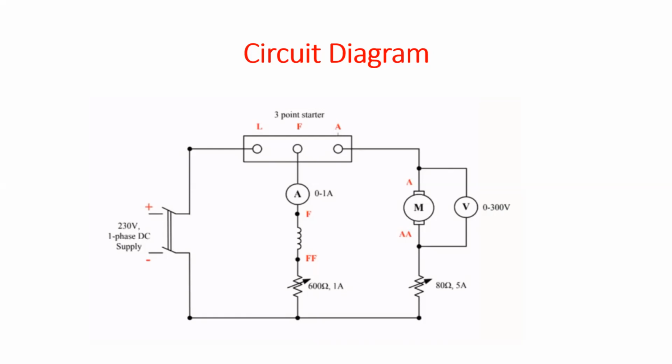Initially, EB is the back EMF, which is proportional to speed. Initially, the speed of the motor is 0. So if motor speed is 0, EB is 0. And VA, if you are suddenly applying 220 volts, RA value is usually very small. In the case of a shunt motor, it is usually 1 ohm. So whatever 220 volts you are applying, divided by 1 ohm resistance, as EB is 0, it will lead to a very high value of IA.